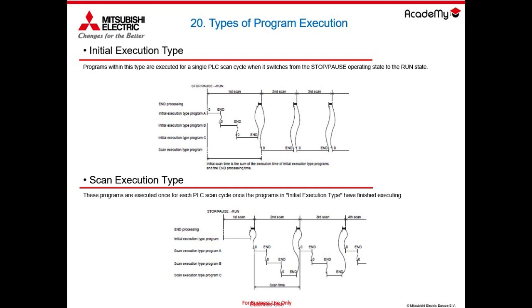Clearly, the longer the execution time required, the more programs we write, the longer the PLC scan will be in terms of time. So clearly, the scan phase will depend on the time used by the PLC to run the various programs.